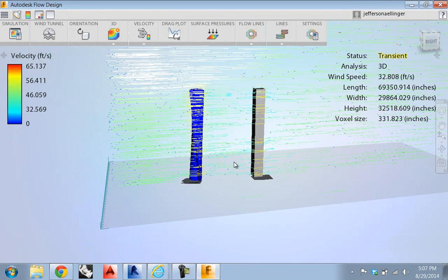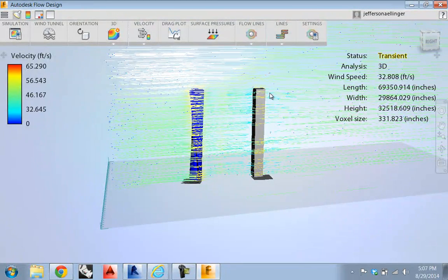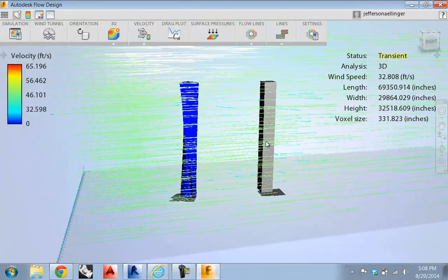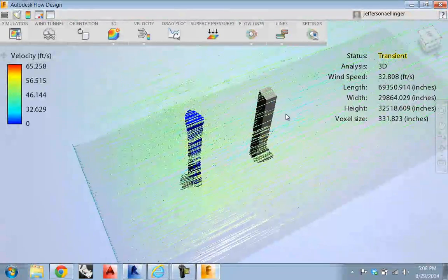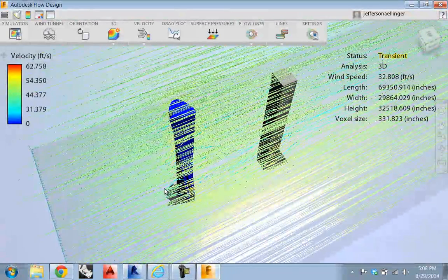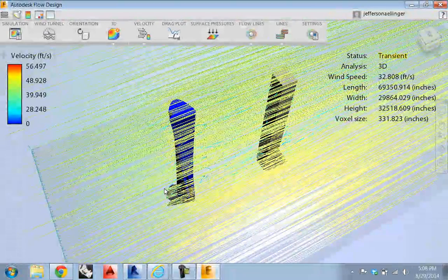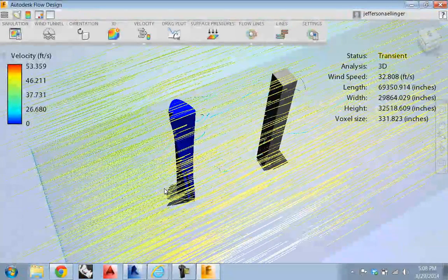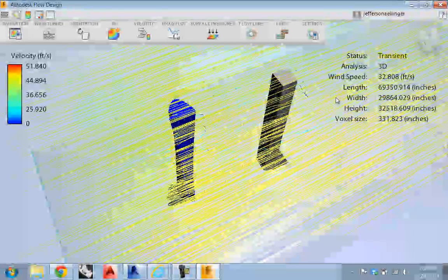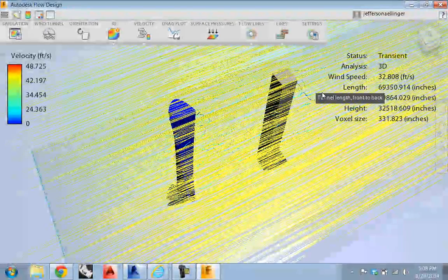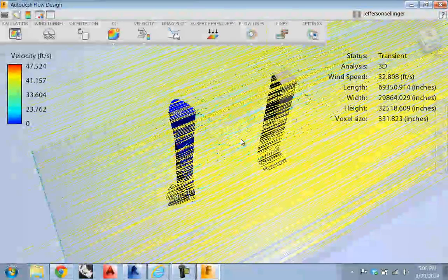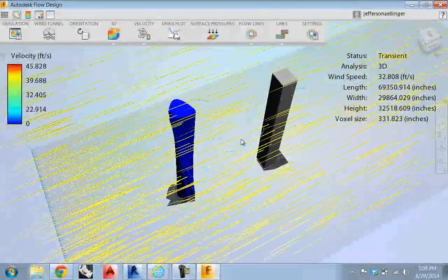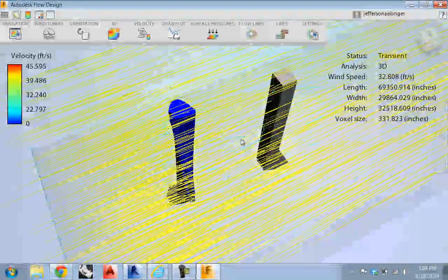And of course, the way the display is working now is we're looking at the streams of arrows, and this is much more useful in terms of understanding how we're disturbing the air, because what we're looking for, at least in load shedding, I'll talk about insulation or trying to pull air in for passive conditioning, we actually want something different. But for right now, if we're looking at load shedding, what we want are streams of air that are parallel, or more or less parallel, right? So that's laminar flow. And laminar flow will not induce that turbulence that generates load on the building, right?